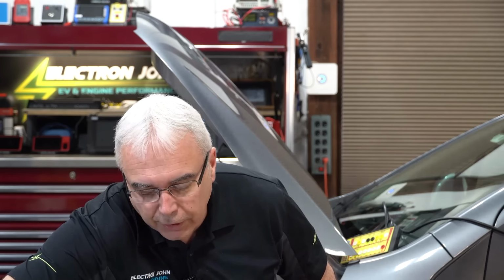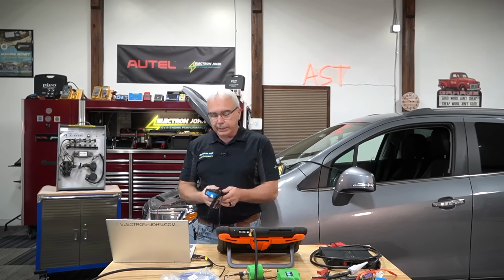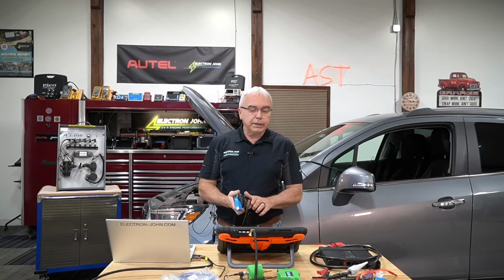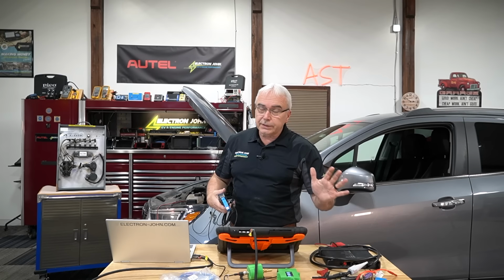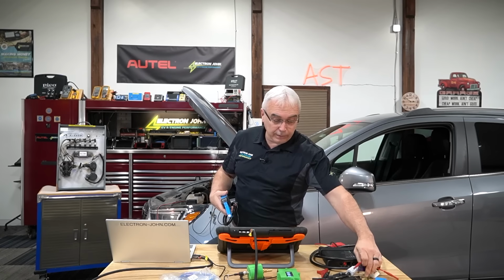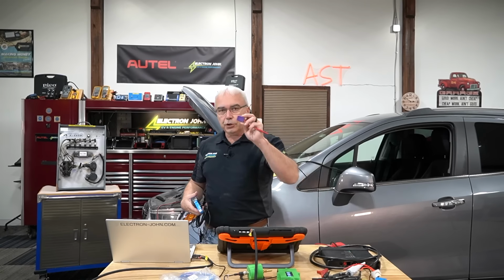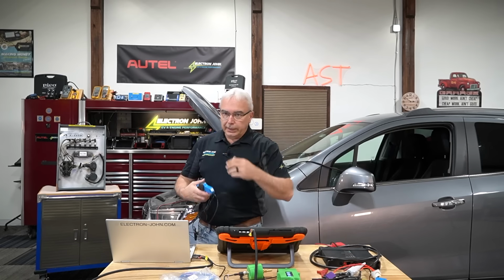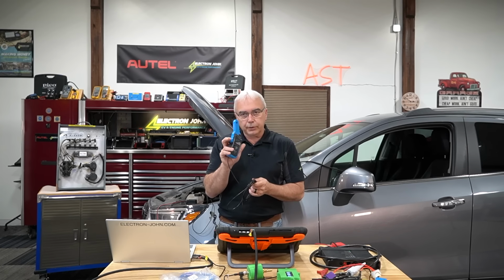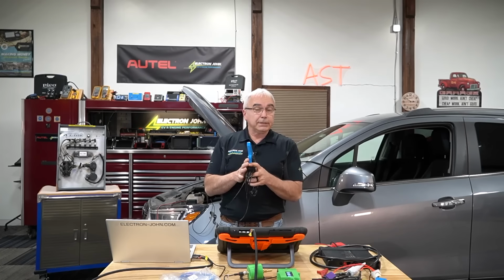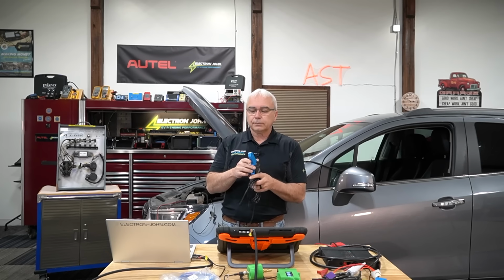So when I start going through this, I'm going to kind of do it quickly on this car. When I start going through this on the car, I'm going to be using pressure transducers. I'm going to be using the ignition system adapters. I actually am going to be using the one from Joe's Auto Electric here, placed right off cylinder number 1. But I'm also going to be using an inductive current probe, right? And I'm going to clamp this around the ignition system as well. So again, it's not going to take a whole lot of time to get these test results.